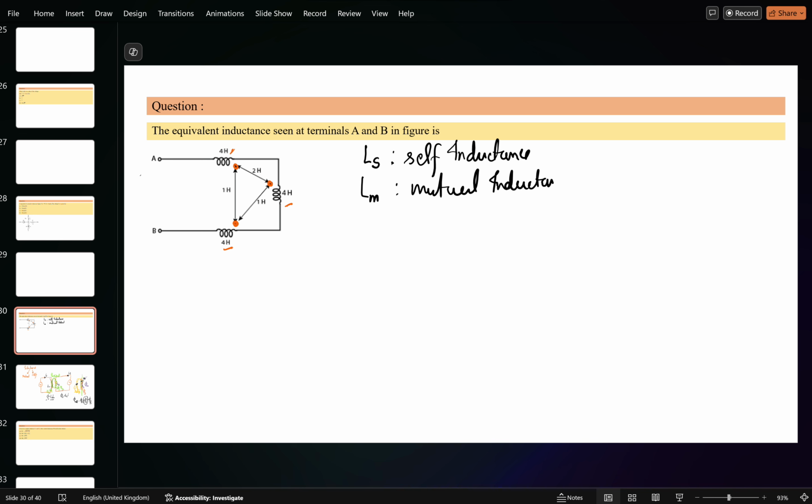And if two coils, suppose these are the two coils, when they are in series, and this is the dot polarity here, it means that the current which is entering here, the same current, in this coil also will enter the positive, dotted terminal. It means that the flux mutually will be added up. Try to see from the flux direction also.